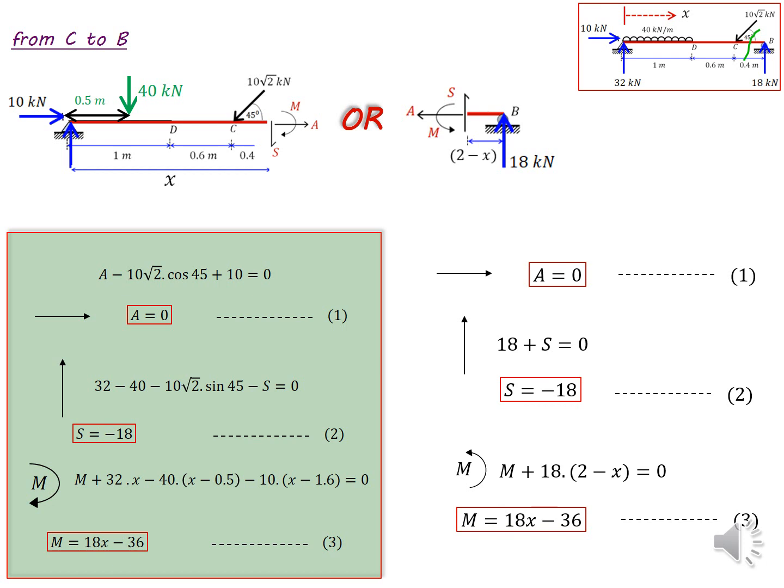But you may have noticed that the notation of the bending moment, shear force, and axial forces is marked differently from left to right side. That's because of following the sign convention. For the axial forces, we say tensile force is a positive one. So from B, I applied the tensile force, as you can see in the figure.